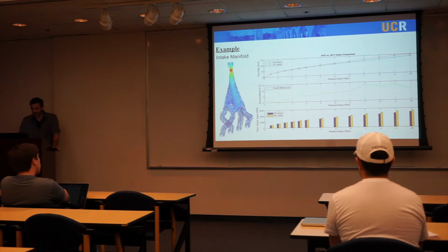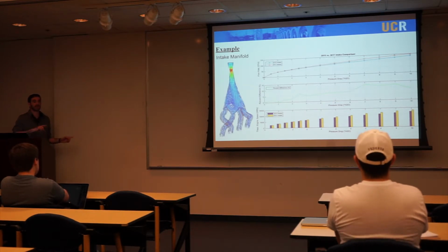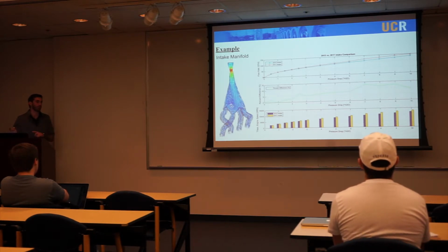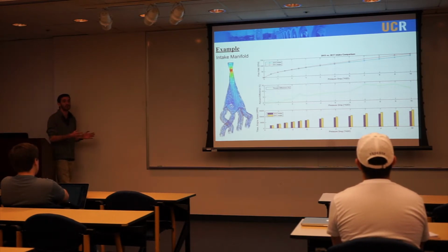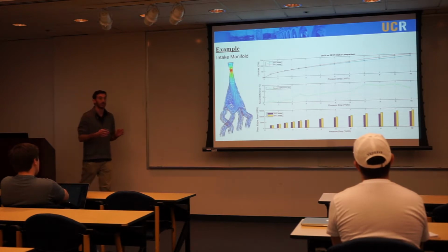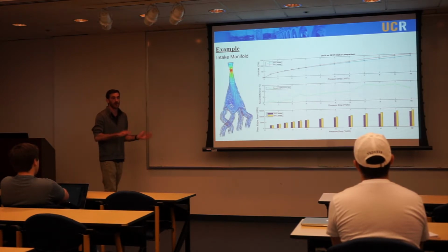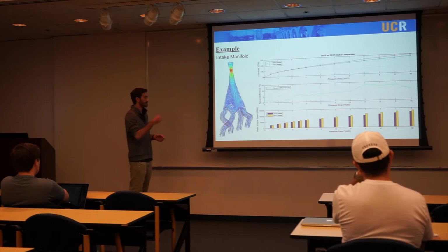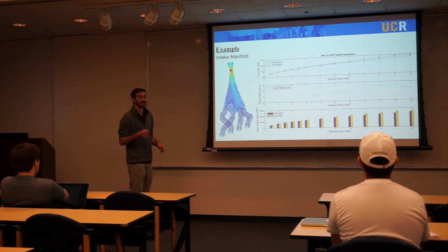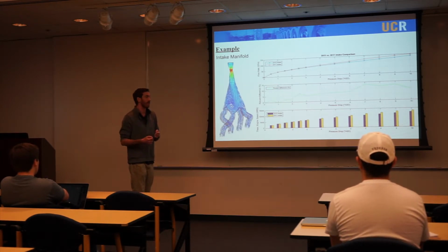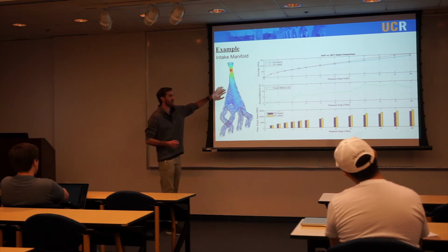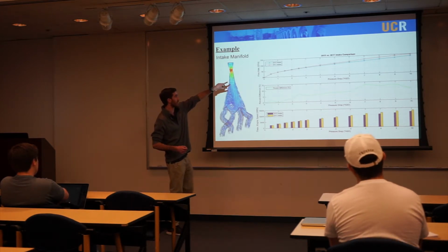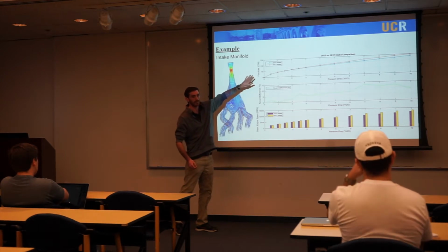And again, I never got to do a prototype of the intake. This is me improving on earlier years' designs. I never did a prototype intake and then an actual intake. But since I was there for sophomore year, I was able to build on my designs and actually compare them to see if we're doing better. Having that specification of what you're trying to improve upon or what your limiting factors are is really important. So here, for the most part, it's all about flow rate coming through it and your pressure drop.